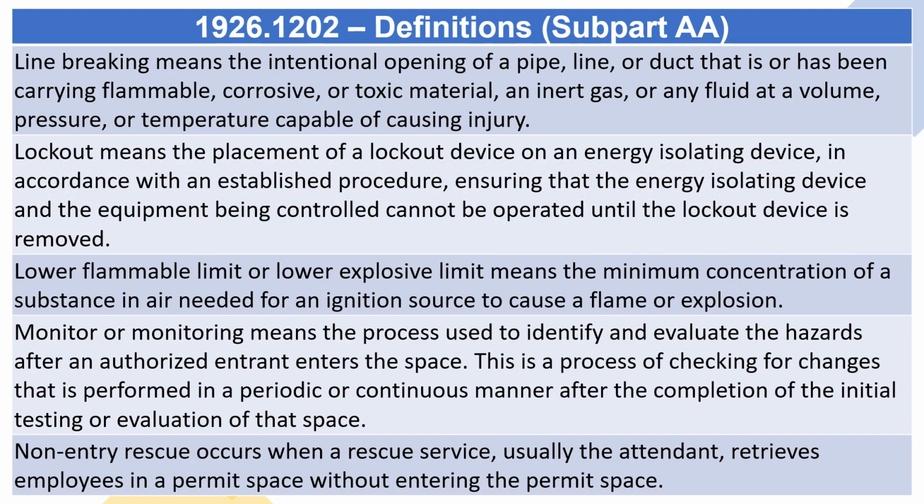Line breaking means the intentional opening of a pipe, line, or duct that is or has been carrying flammable, corrosive, or toxic material, an inert gas, or any fluid at a volume, pressure, or temperature capable of causing injury. Lockout means the placement of a lockout device on an energy isolating device, in accordance with an established procedure, ensuring that the energy isolating device and the equipment being controlled cannot be operated until the lockout device is removed.